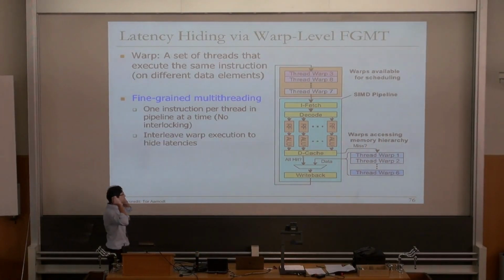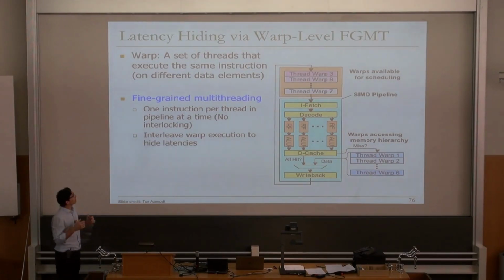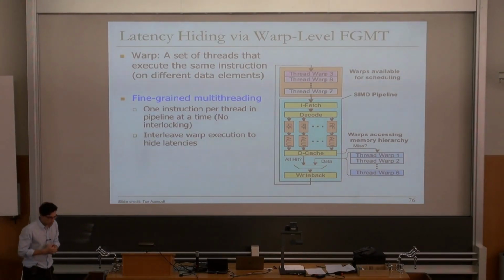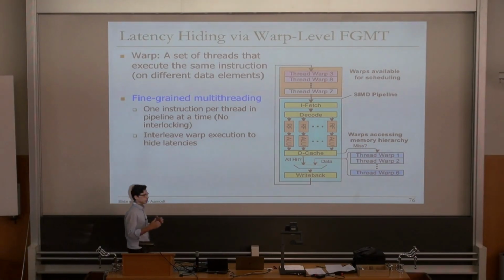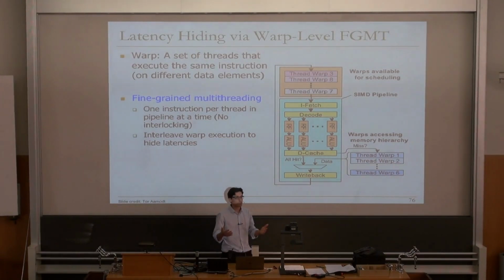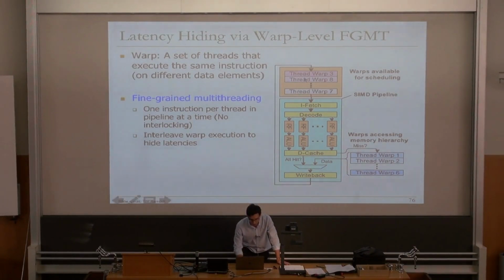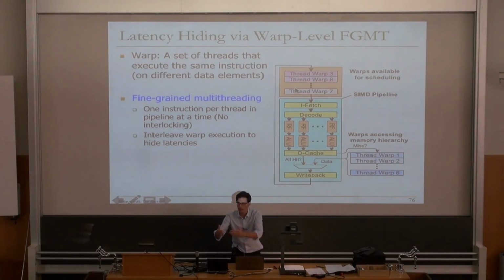One of the advantages of the GPUs is that they execute this fine-grained multi-threading. Recall that I just said the warp scheduler is able to schedule whatever instruction is ready to be executed. We talk about eligible instructions. And observe that depending on those ready or eligible instructions, the scheduler will decide, for example here, to issue one specific instruction, maybe a load instruction or an addition instruction for warp 7, and then for other warps, and then here warp 8, and then here warp 3.